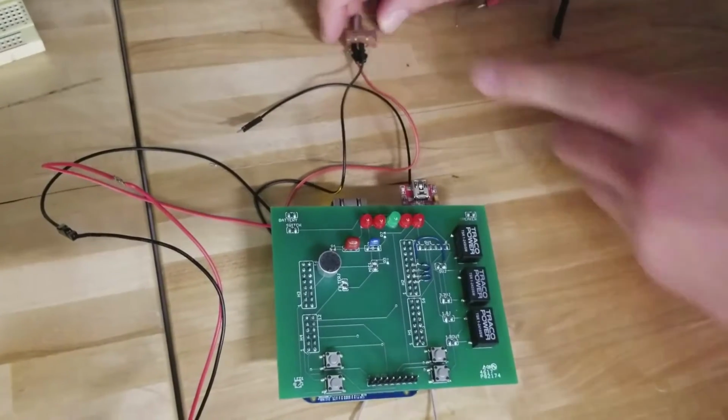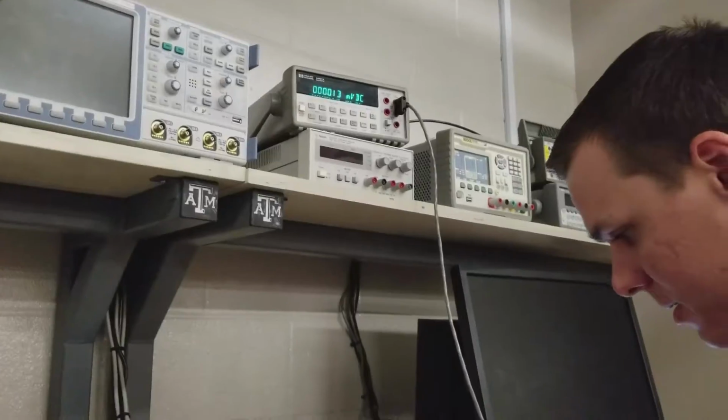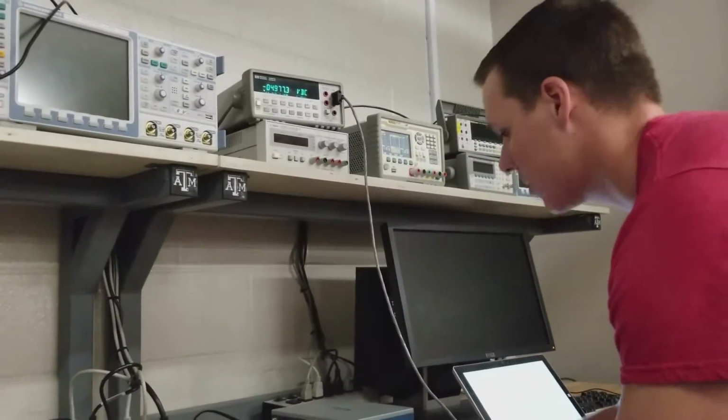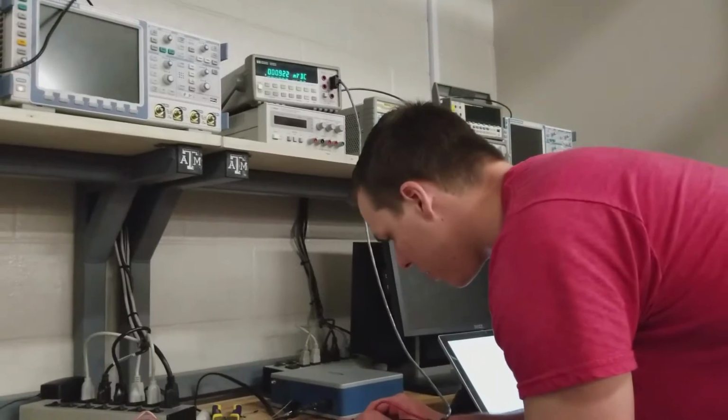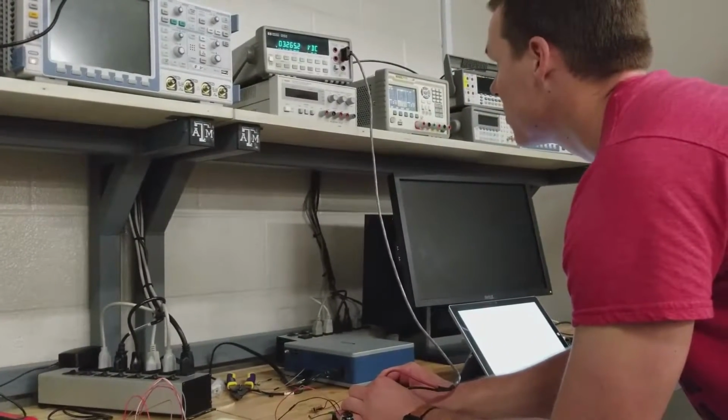Power flows to 3 Traco power buck converters, stepping down the voltage to 5 volts, utilized by the microcontroller and display, 3.3 volts, utilized by the buttons and ADC, and 1.8 volts, utilized by the LEDs.